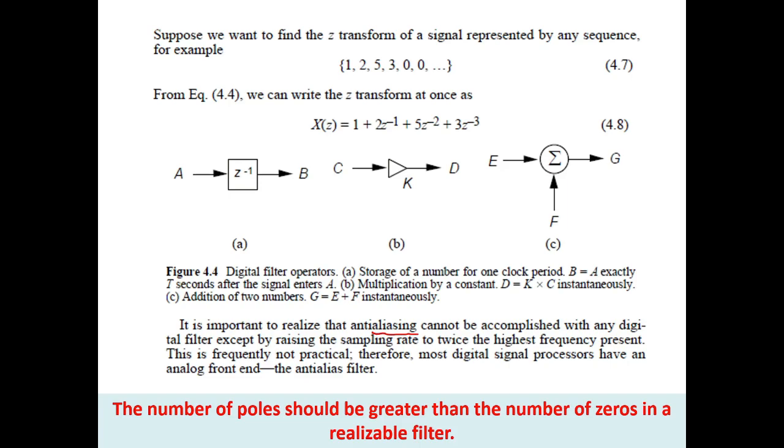Or even if it is following the Nyquist rate, and we are using a low cost device, even if ideally your sampling is okay, due to the non-ideality of many of the components there will be some spectral leakage, and there you will have aliasing.